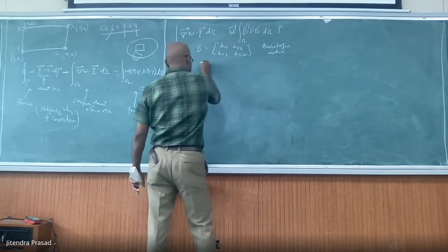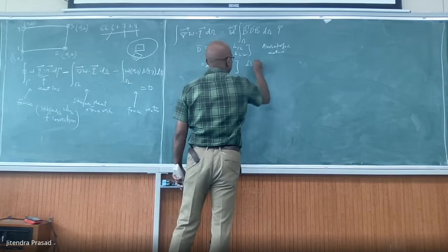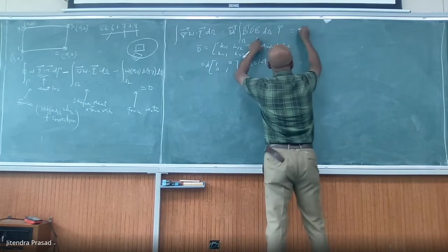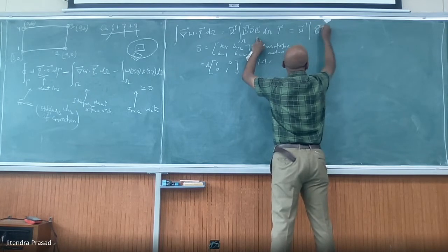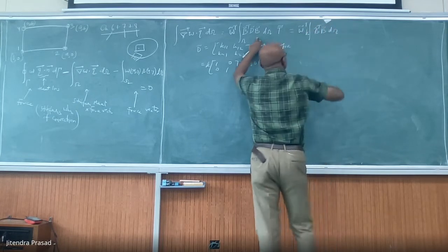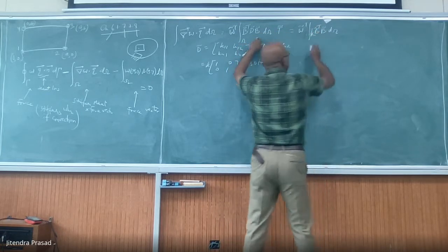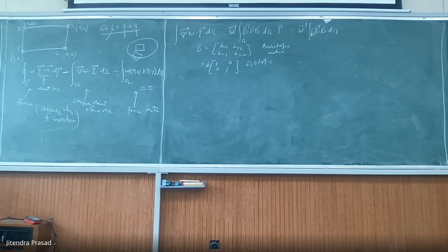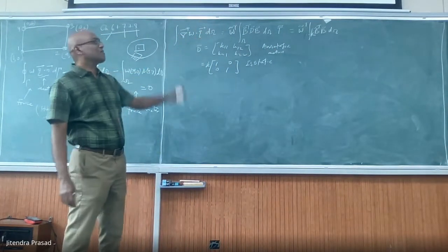Otherwise, this will be equal to K times the identity matrix for isotropic material. So all this is repeating; we have done it already. Basically we can also write this as the integral of B transpose B d omega times K. If K is constant, or even if K is varying but isotropic, it may be isotropic but not homogeneous. Homogeneous means the same value everywhere, so in that case K may be a function of x, y, and hence it will be inside the integral. We know how this varies. Finally, it comes.